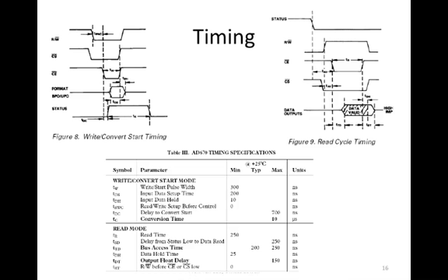So in certain cases, if your controller chip is running at a higher speed, and you do not consider this delay, you end up having the processor reading a value that is not the true output from the ADC. That's some garbage value on the bus because you're reading too quickly. So there are cases where these timings are very important.